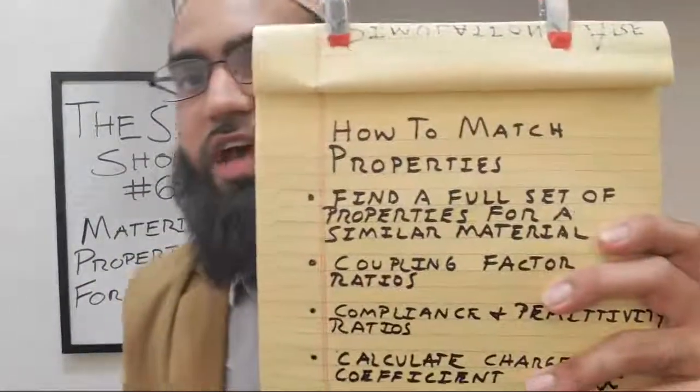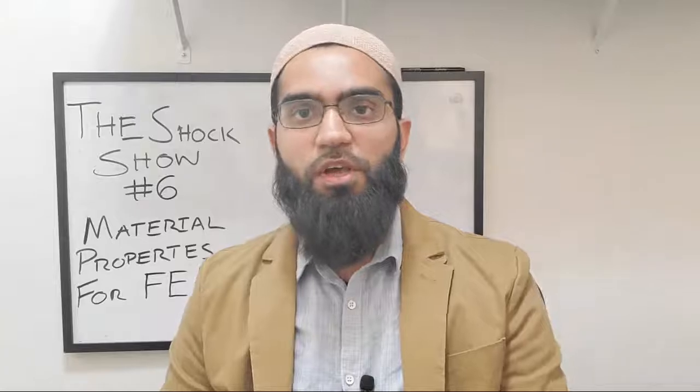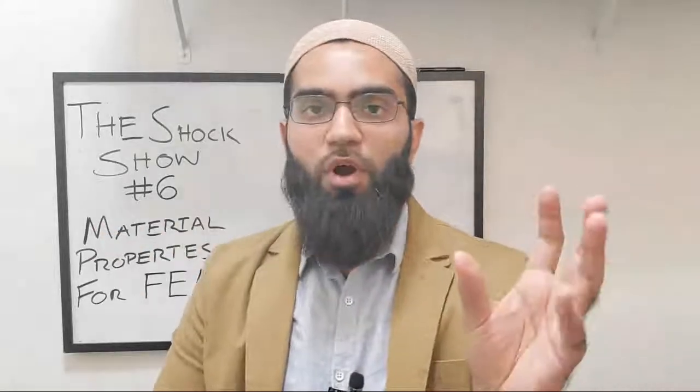The first step is to find a full set of material properties with similar behavior. So you have a soft PZT, you find a full set of properties for another type of soft PZT. It's not going to be the same as your material, but it will be similar in terms of properties. And then we establish our baseline set of properties for, let's say, our disc.